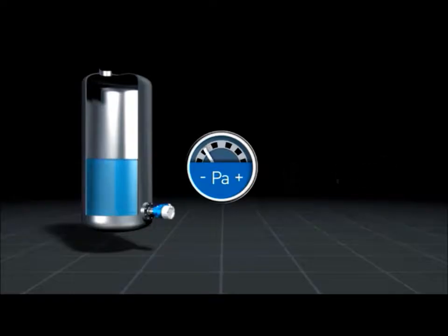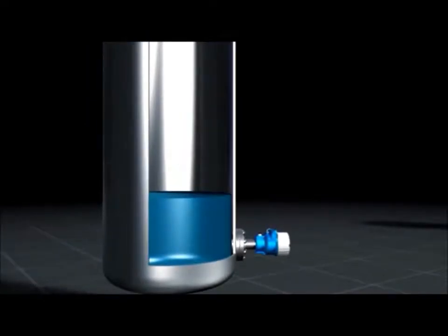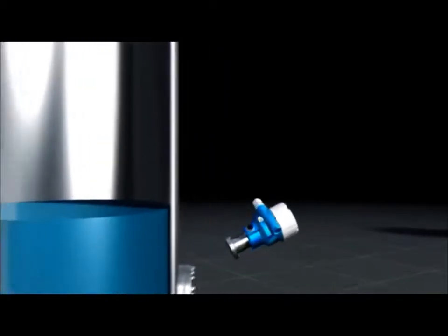of the medium. In an open tank, pressure is continually compensated in relation to ambient air. Therefore, the gas in the upper area of the tank does not affect level measurement. However, in addition to the pressure of the liquid column, the atmospheric pressure also acts on the sensor. In atmospheric pressure compensation, the sensor is called a gauge pressure sensor. Let's have a closer look at such a sensor.